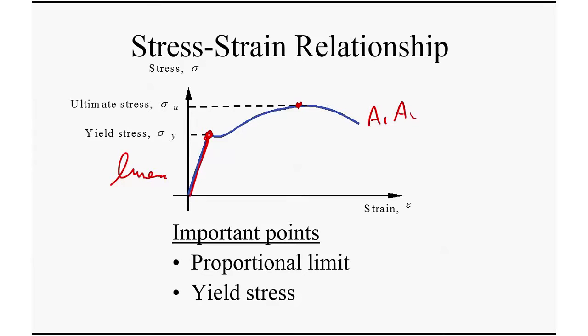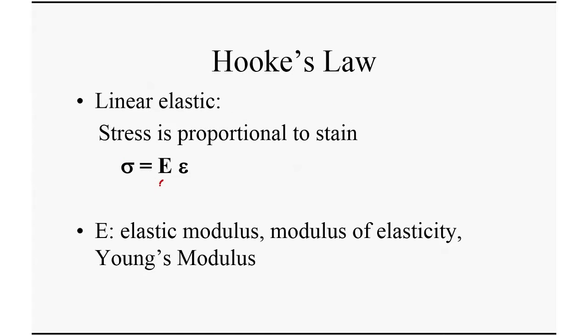You can put it the other way, right? And also there is a ratio here, the modulus. We call it modulus because it shows how stiff the material is when you deform. So this is a ratio, right? E is a ratio, sigma over epsilon. And this has a name called Young's modulus. See, another guy. It's not an easy task to find this one equation. Two guys contributed, got the two names, right? Put all this in here. So Hooke's law, but the ratio is called Young's modulus.